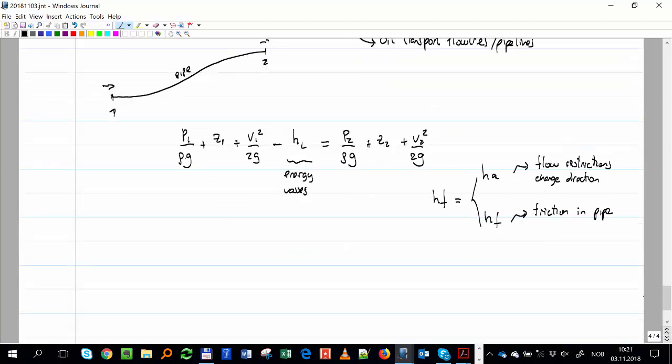But at the end, if we had, for example, the subsurface safety valve in our tubing, it could cause a restriction. In that case, we can model restrictions as an equivalent length. Thus, almost always we use this HF.